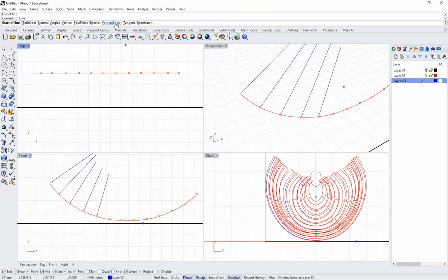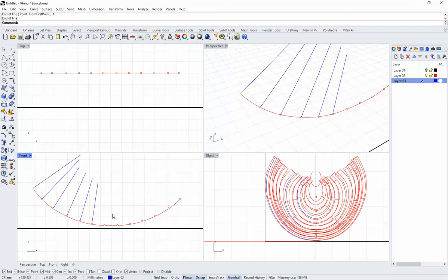And we can just work through it. You can probably also activate the command, hit P, enter, click, F, enter. Yeah, it might be a little bit faster, depending on how you like to work.